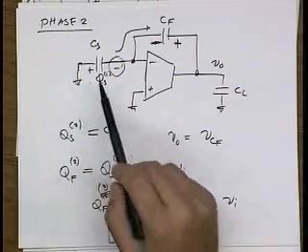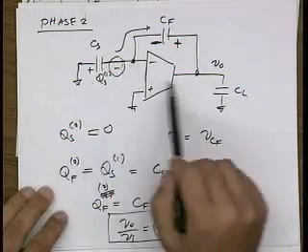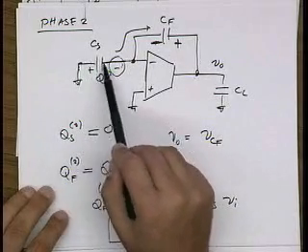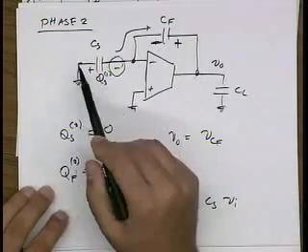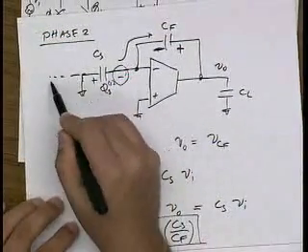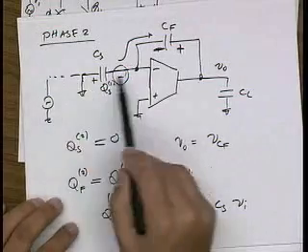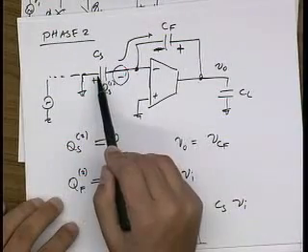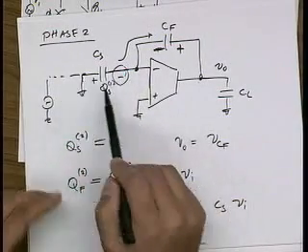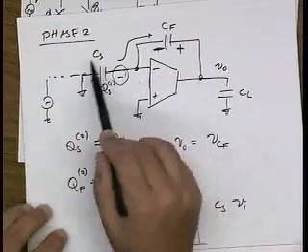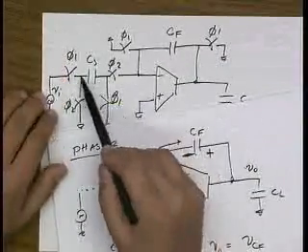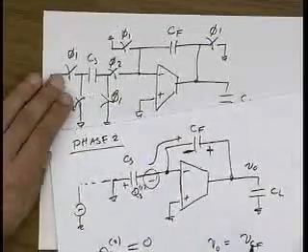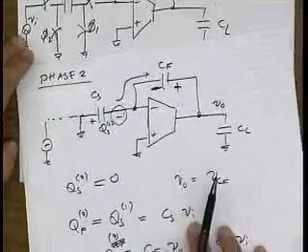That's right. So look at this input capacitor. It's connected across this, and basically it's inverted. The top plate was grounded, and the bottom plate was presented with the input. If this were a regular amplifier, then you could see that definitely you would get inversion, because this would be the top plate and this would be the negative plate. But what I've done is I've actually flipped the capacitor over. In this process of grounding it, I'm flipping the capacitor charge, and so I get a non-inverting input. Okay?